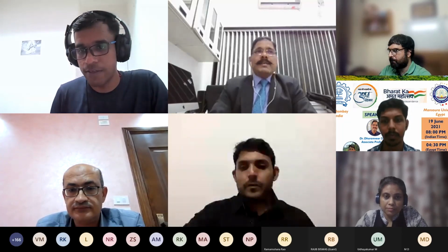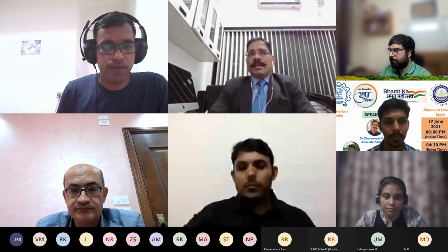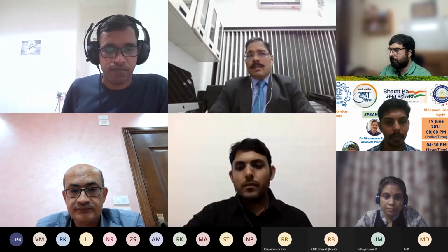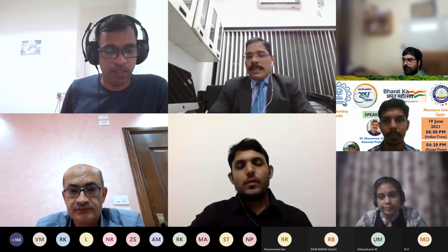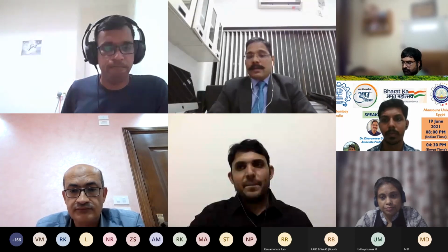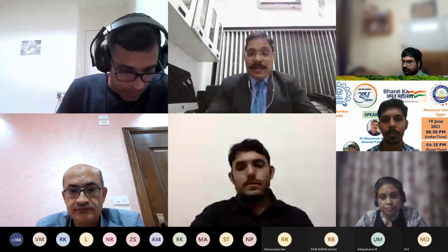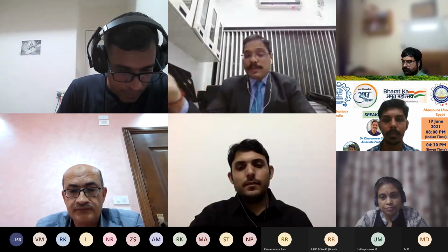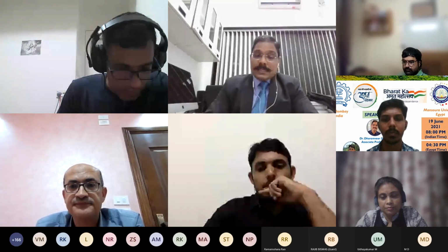Yes, sir. Yeah, Praveen, I think if you summarize in one line, the source of the unmodified binder plays a very critical role in the modification also. Sometimes the same polymer will work over one particular kind of unmodified binder, but it may not work for another source of the same virgin binder actually. Yeah. So this plays a critical role.